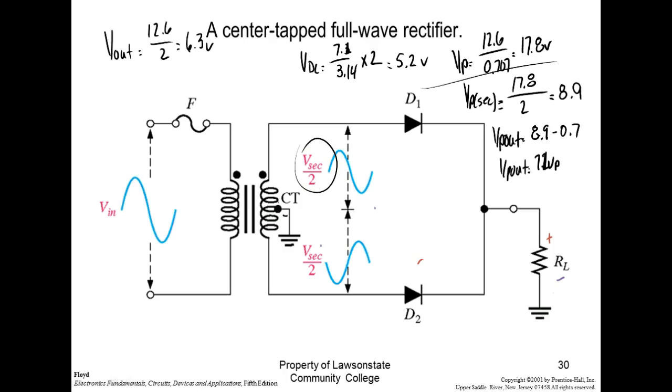Are these diodes in parallel? This is another big mistake people make when they hook up. Are these diodes in parallel? They're not in series, because if they were in series, they would be wired like this. And they're not wired like that. Now you were right when you said no, but you gave me the wrong reason. They're not in parallel because the cathodes are connected together, but if they were in parallel, the anodes would be connected together. And what's between the anodes? Well, we got a dang transformer between the anodes, right? You understand that? So no, these are not in parallel.